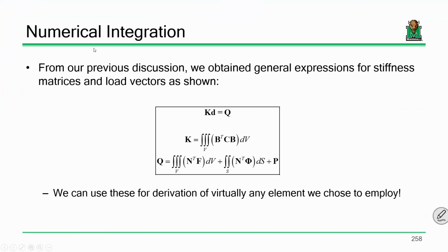Okay. So to summarize where we're at so far, we're here. In other words, this whole semester so far has really been enveloped with a single equation. The fact that stiffness times displacement equals the load applied. And that's been the spirit of everything we talked about this semester. The difference between a direct stiffness approach and finite elements is simply this: how you get the stiffness matrix, how you get the load vector.